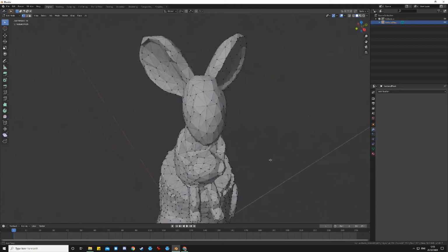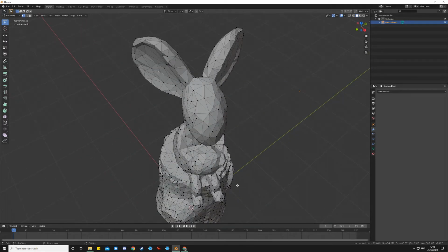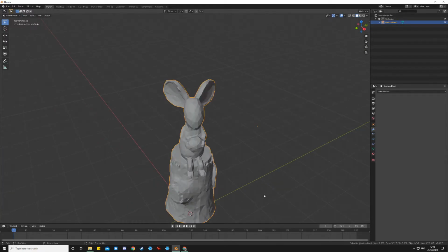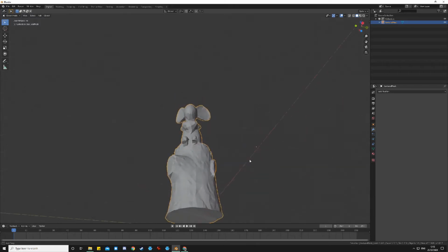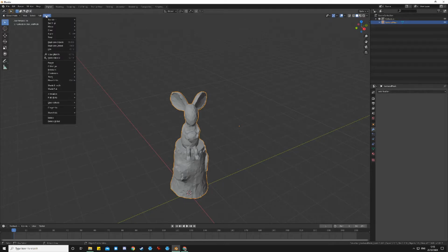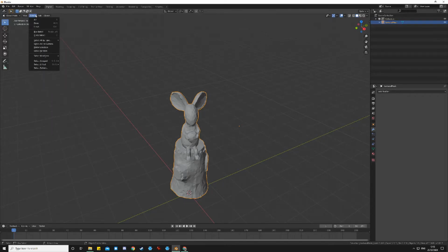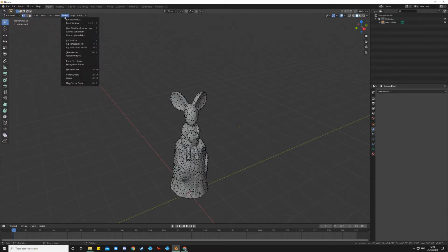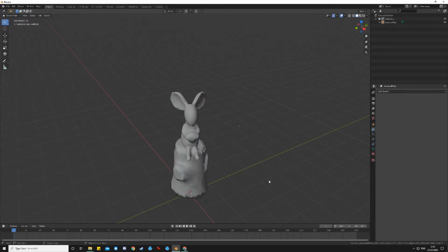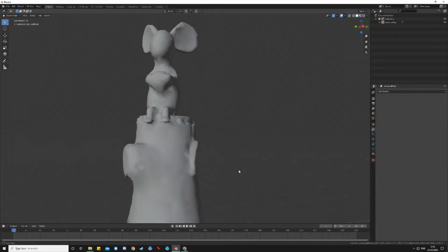What's the next step? There's no holes in it, which is brilliant. So we've done the filling, and now we need to do some smoothing. So go back to object mode, and we'll get to see the blocky version of it there. But what I'm going to do is press object, sorry, is it in edit mode I need to do it? It is in edit mode. You go to faces, select all, and then you go to shade smooth. So now that's made a nice smoother version of all those objects.